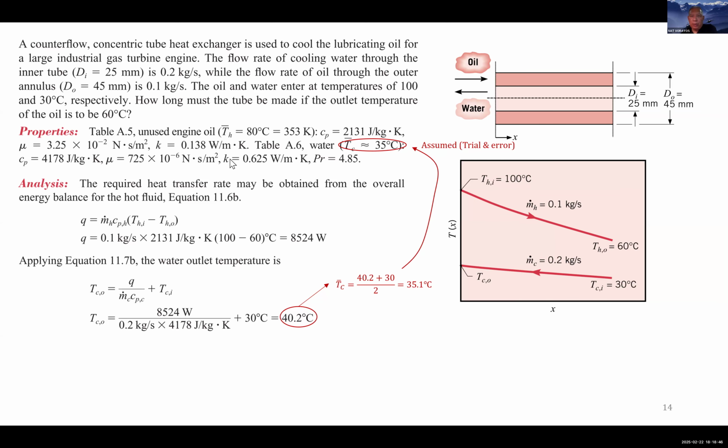Okay, so then now, because you're going to use the third equation, and you already know Q, and judging from the fact that even though the problem specifies you with 3 temperatures, hot fluid inlet, hot fluid exit, cold fluid inlet, in the previous step you found TCO, the exit temperature of the cold fluid.